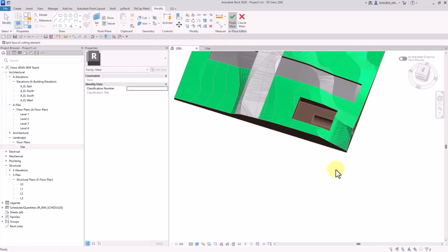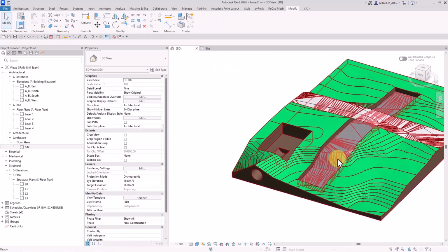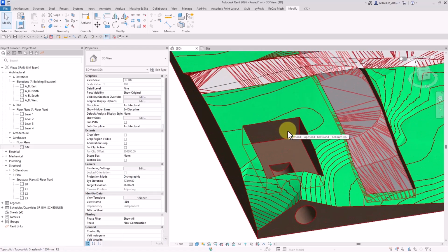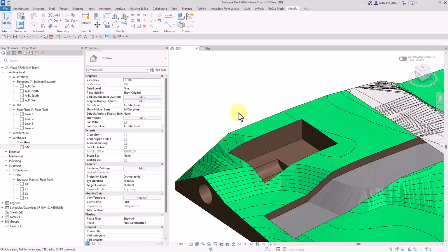Now, the reason that we face almost no limits when we want to create cuts is that when we try creating cuts using voids, the software might detect some problems with the form of our voids. In this case, Revit would automatically modify the form, not severely, just a little bit, so that a cut can be created out of that void.